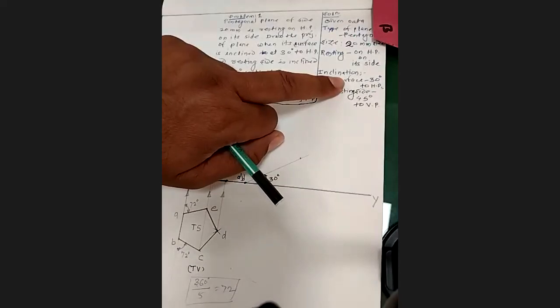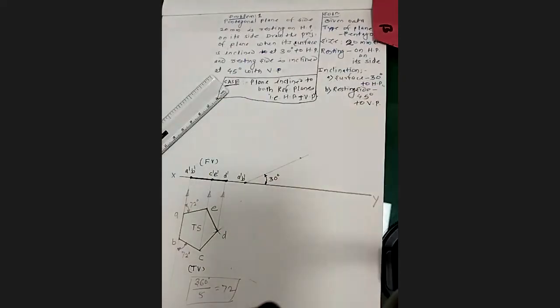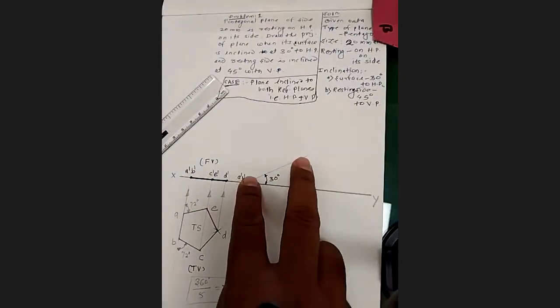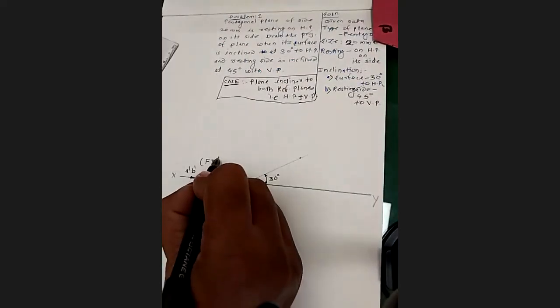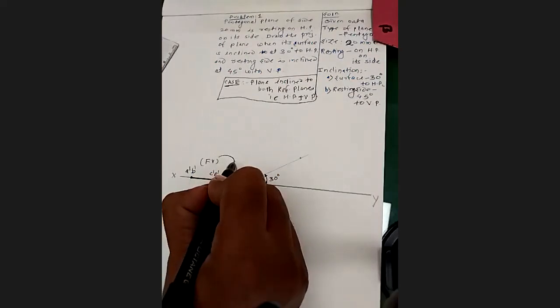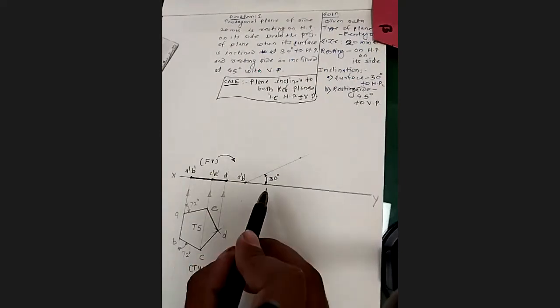This angle, the given surface inclined 30-degree with HP, is what I have taken. Then what will be the length of this? See, this line view, we are going to turn it with the given inclination as it is in the second stage. This is stage number 2, taking the inclination of the resting plane with the concerned line or surface, or whatever is mentioned.